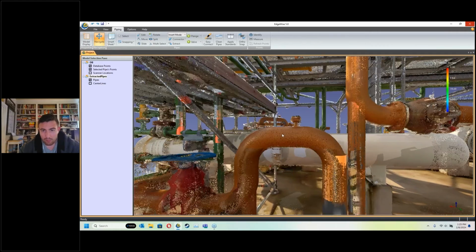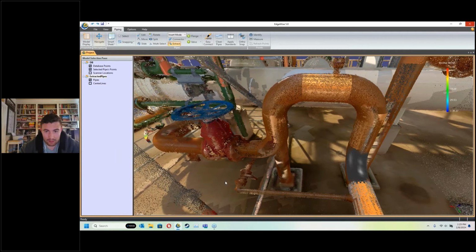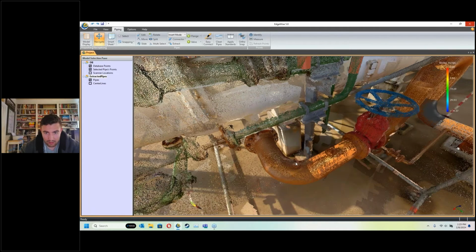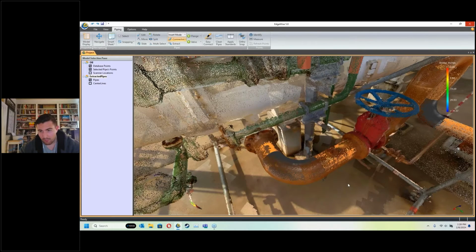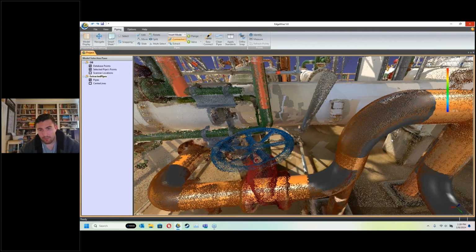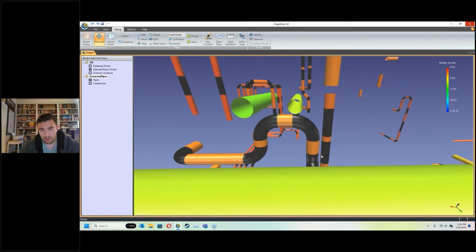And then global would be like, on this unit, local accuracy, if you're standing on one of those elevated platforms and you're looking at maybe an exchanger to your right and then some piping to the left, a few dozen feet away, that would be local accuracy. Global would be some of these elevated platforms back down to a point that's maybe below you at grade that you can't physically see from your perspective, so they're completely distant from each other and disconnected visually, that would be global accuracy. So across the entire data set, definitely significant accuracy.